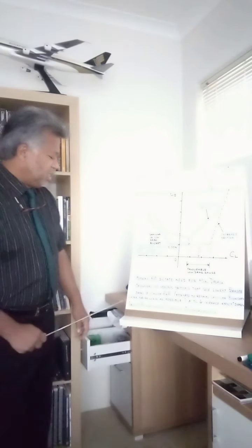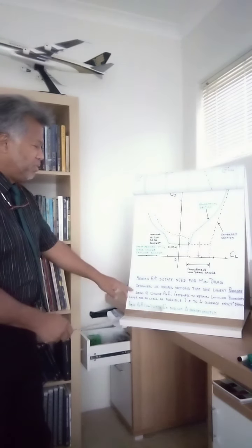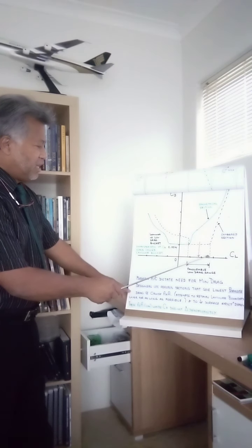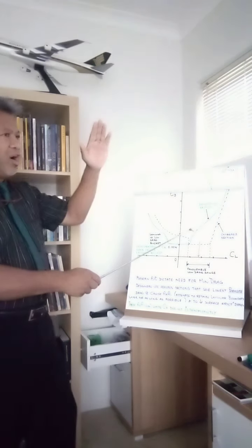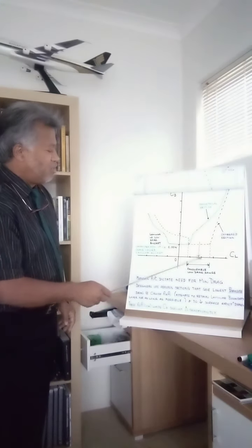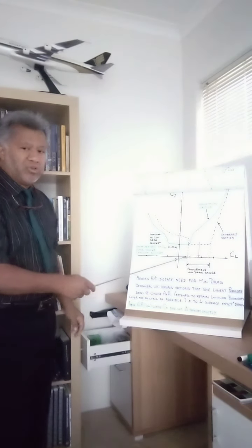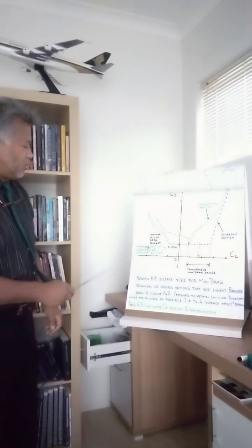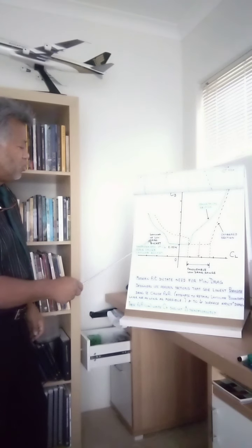Okay, so the angles of attack are usually low, not high, because the drag would become excessive. So you have what they call a favorable low drag range that the manufacturers try to aim for. It's also known as the laminar or low drag bucket.